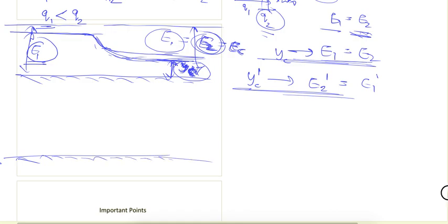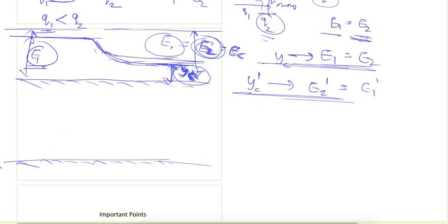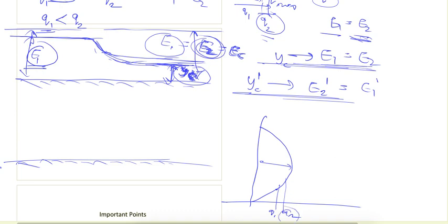And similarly it will happen if the incoming flow is in supercritical condition. From the same graph we can see, this is Q1, and if I increase it to Q2, as we reduce the width, this unit discharge will increase to Q2. So here it is associated with an increase in the depth. If the depth was here for supercritical condition, then when the unit discharge is increasing because of the reduction in width, the flow depth will also increase.